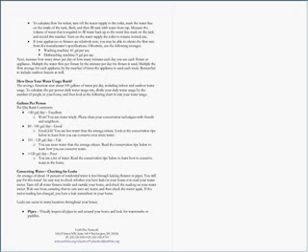In order to find out how your water is being used, you can estimate water usage directly from the faucet. This is slightly less accurate, but it will indicate how each point of use is using the water. So be sure to test the indoor and outdoor faucets and shower heads by turning on the faucet to its normal flow and holding a container underneath and then measuring the quantity of water. Let the water run for 10 seconds and then multiply by 6 to calculate gallons per minute.